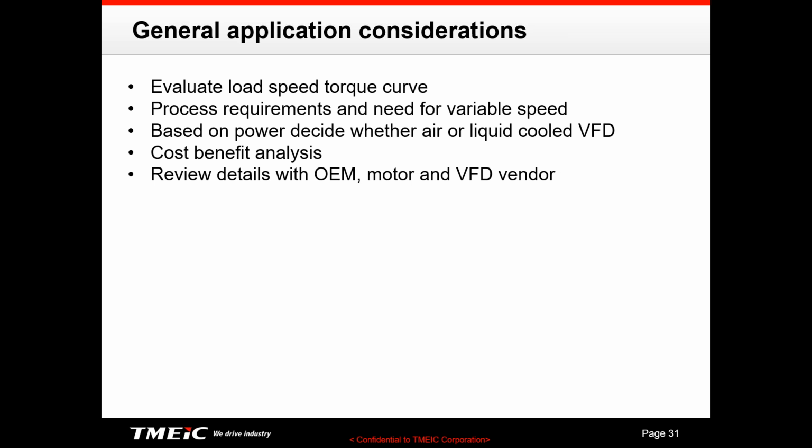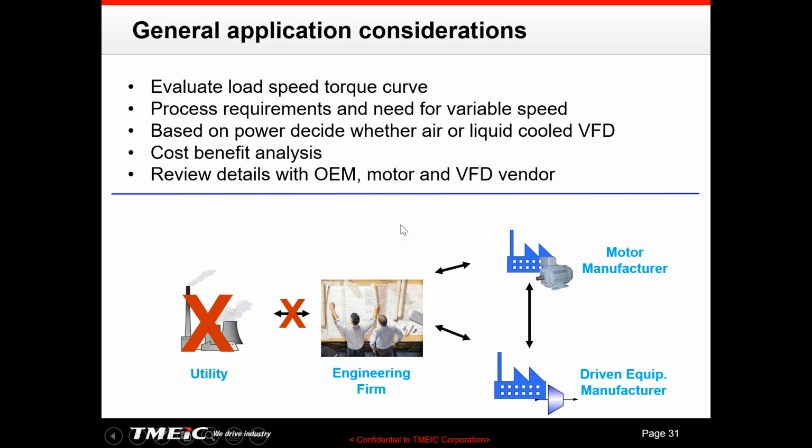What are your overload requirements, things like that. If it's a full-time VFD, of course, we need to include the utility people. But if it's only for the starting function, then we don't really have to talk to the utility people. We can just make a decision among the motor people, the driven equipment manufacturer, and the EPCs.